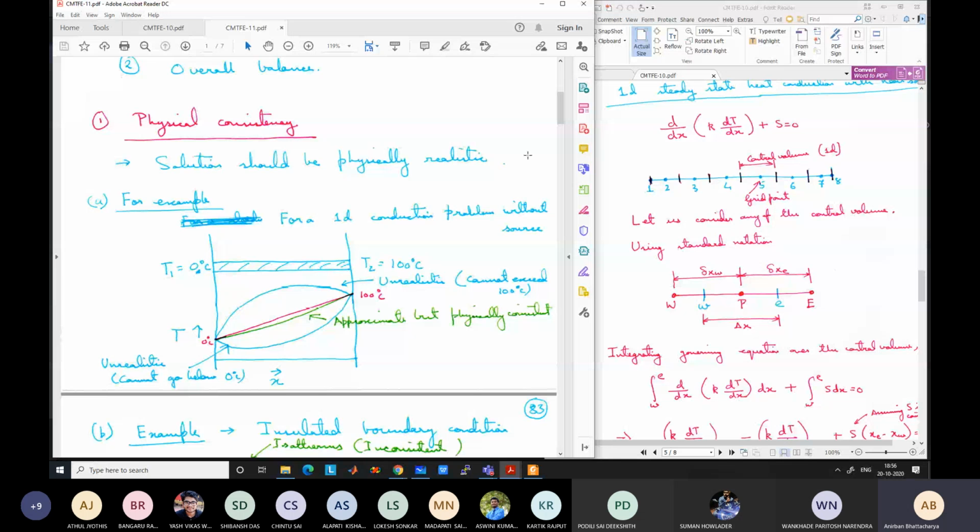But even if the solution is stable, it may still be physically unrealistic. You are going to some values, some convergence, and still it may be physically unrealistic. For example, say we have made some mistake in the discretization of the sphere problem that I was telling. We have put an iron sphere in a furnace, and our solution is giving that the final temperature is minus 30 degrees centigrade. But it is converging to minus 30 degrees centigrade, not going to infinity. It is slowly converging to minus 30 degrees centigrade. So it is physically inconsistent, although the solution is stable. So these are all different things.